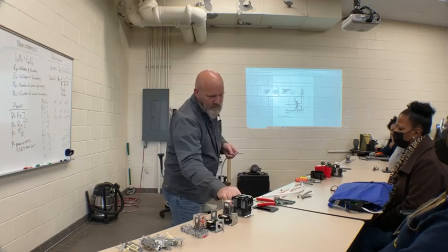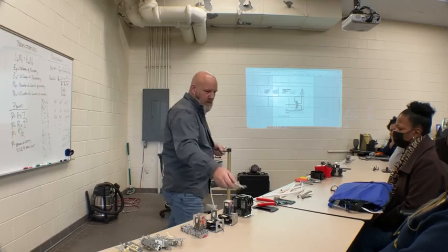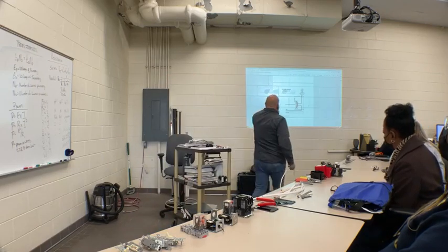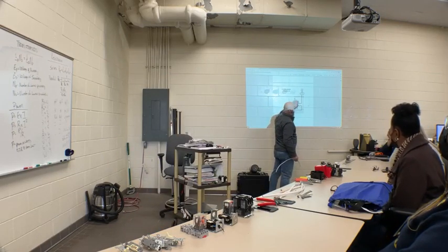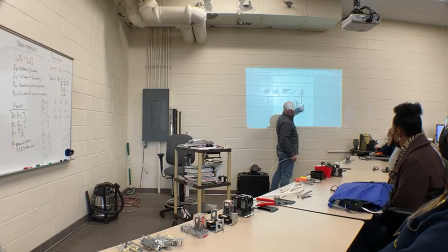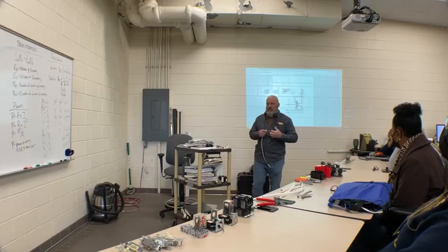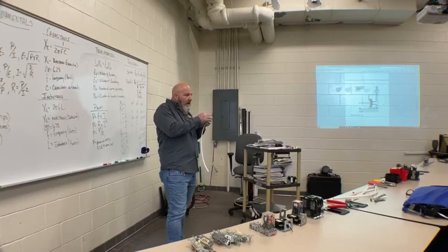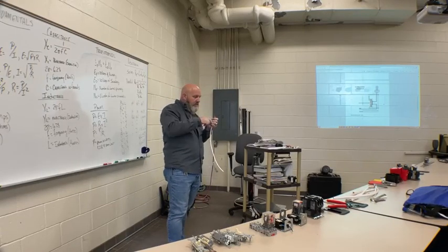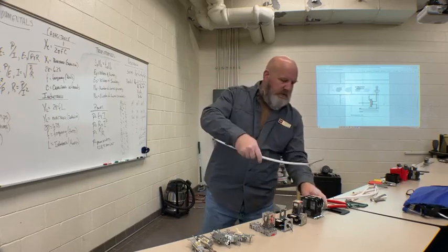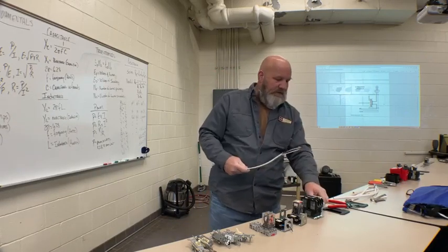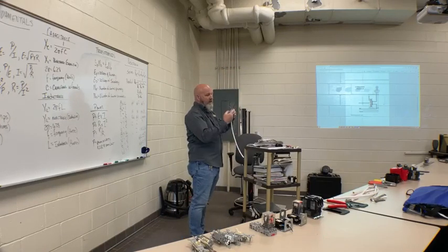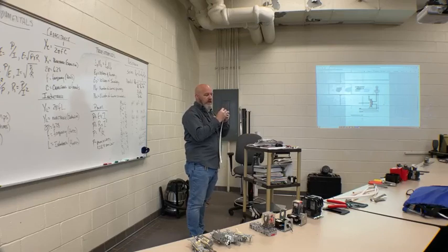Okay. Now, in a receptacle box, in a switch box, you bring power to your switch. This is your switch. There's a box. Your white wire gets connected. In some older work, up until about 2014, you would use the white wire to bring power. You would actually look in a box and see a black and a white, and the white would have black tape on it. People would run power to the light and come down with the black and go back up on this leg to power the light. It's called a switch leg.